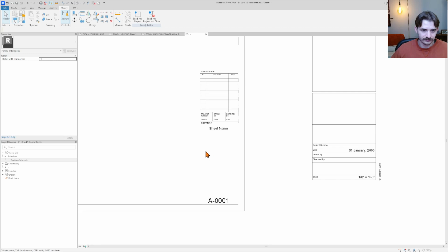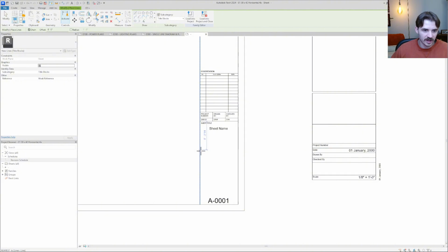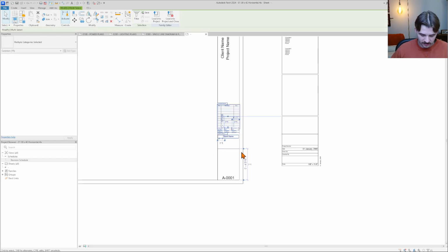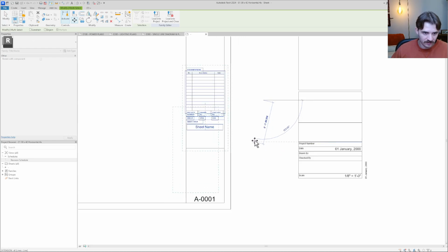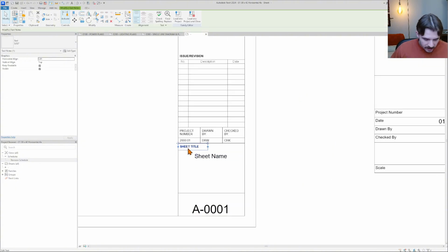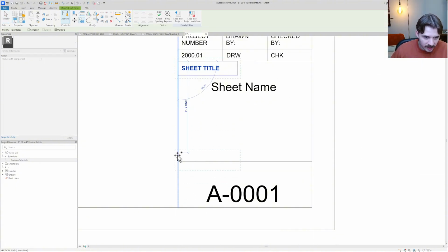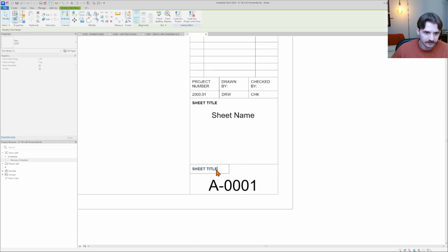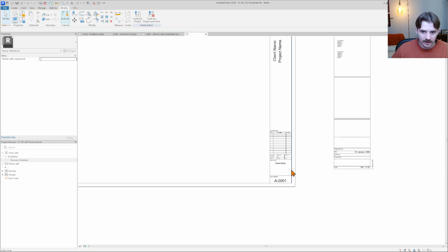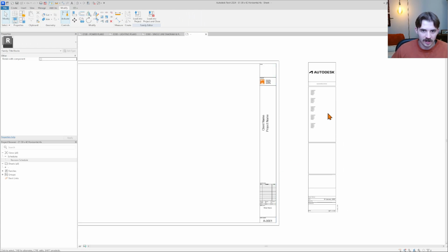And we can draw another line. We're going to have some extra space, I think, down here at the bottom. So let's actually start shifting this stuff down so I can draw a box. Type in MB on my keyboard, pick a base point, and basically just move this thing down. I'm going to want to move straight down, so that will be good. That looks good. Copy here. Use this base point again. Sheet title. Sheet number. And that pretty much does it for creating this title block.